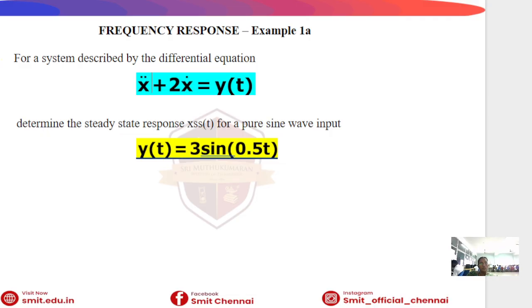For the magnitude plot, we have to find the corner frequency. The corner frequency is found from the transfer function: in the a plus jb format, it is the real constant divided by the imaginary constant. For every complex term in the transfer function, we have to determine a corner frequency. For example, with three complex terms in this transfer function, we have to find three corner frequencies: omega c1, omega c2, omega c3. Then we have to draw one table.